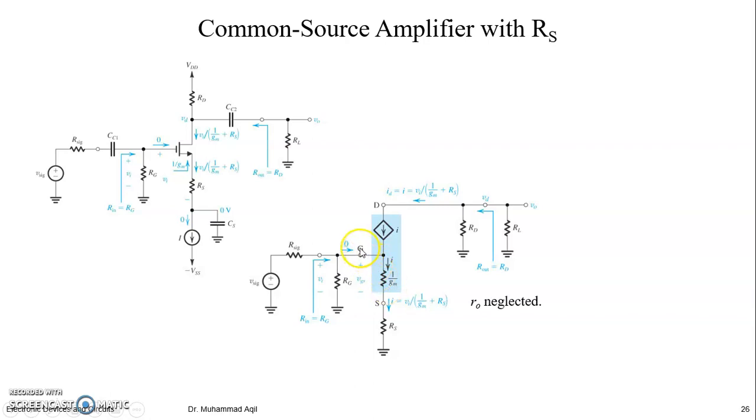the gate. Although it looks like you have a resistor between gate and source, remember, even if you are taking T model, it's not showing here explicitly, but you know there is no IG. Gate is insulated in MOSFET, right? So your Rin is RG, right? But whatever signal VI you have from this gate to ground is appearing here. So it means VI is from here to here. Then what about the voltage across this resistance? It's simple voltage divider wise. This resistor divided by this resistor plus this resistor into VI will be your VGS, right?